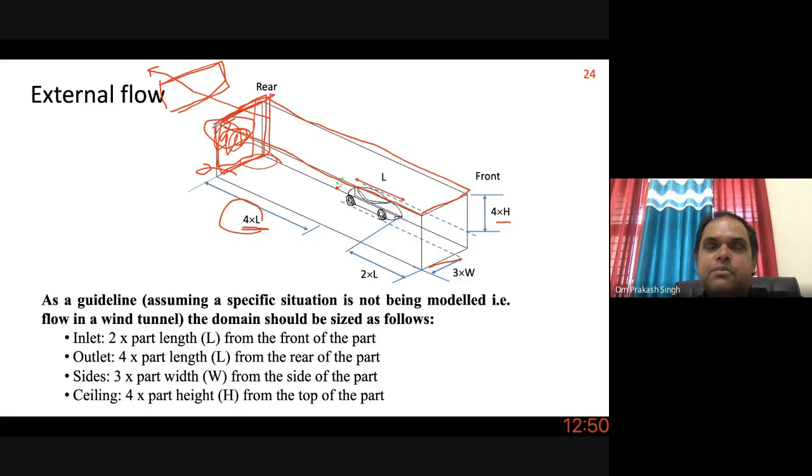a constant pressure, which the physics of the flow is not allowing because of the lot of recirculation. Pressure will drop there because of a lot of mixing, or sometimes it will have different behavior. Then the software will not be able to get a converged solution. So even that is one reason why you're not getting the correct result or getting a diverging solution.